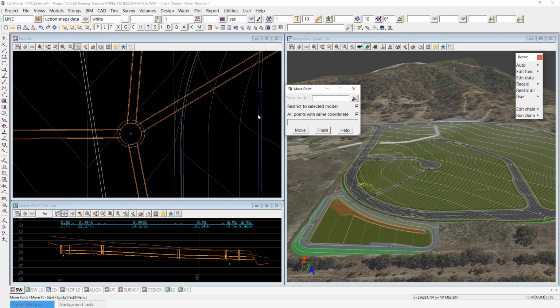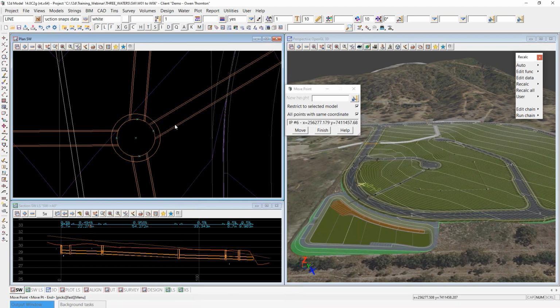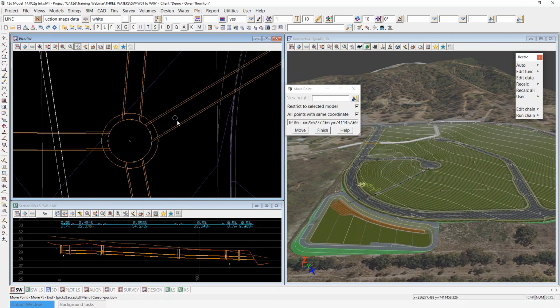And again, I'll tick on the tick boxes, don't really need to, but I can, as well as moving the center of the node, this option is fantastic for moving the connection points once you've changed the connection point mode. I can slide that pipe wherever I like around the perimeter, and I might move it there, move it there, that'll do.